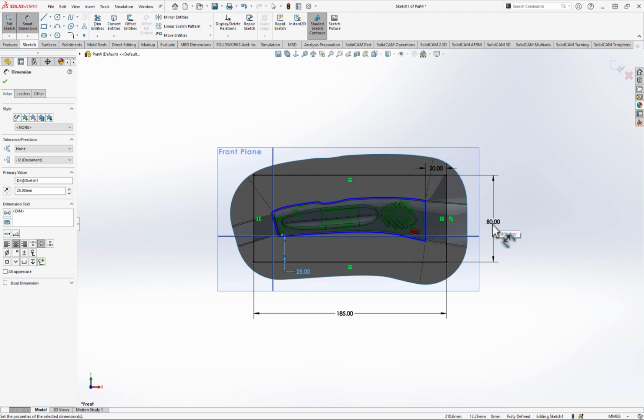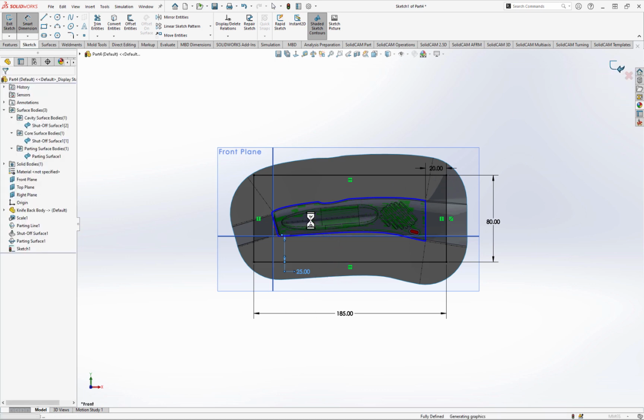But given that we're going to have to machine this from a block of material, it would be nice to have a round number, so a number that doesn't have many trailing decimal places for the overall width and the overall depth of the mold. So that's why I wanted to set these manually and then just put a couple of offsets in there. So I'll OK that sketch,